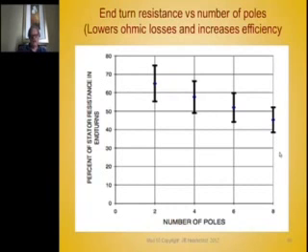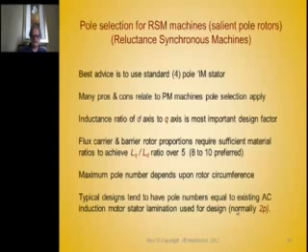You can see how that is, it's quite high for a 2-pole machine. Half to 75% of the total resistance of the phase windings are in the end turns. That means that all that copper is eating up voltage. It's creating heat, but it's not producing torque. The only parts of the conductors in the phase winding that produce torque are the ones that are down the slots that link with the flux from the rotor. And as you could see, that percentage drops to 40 to 55% for an 8-pole motor.